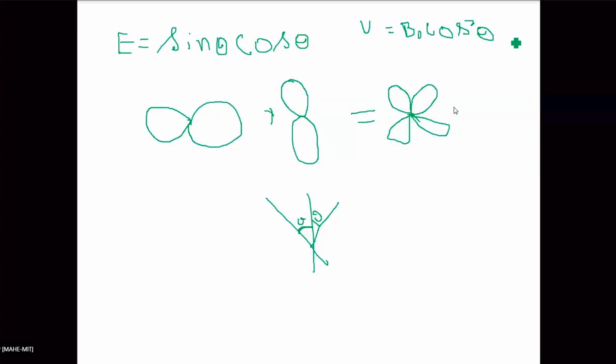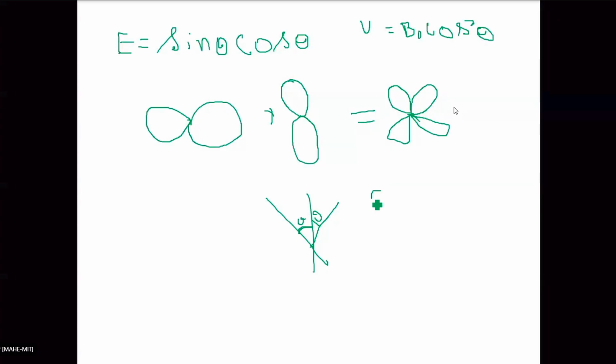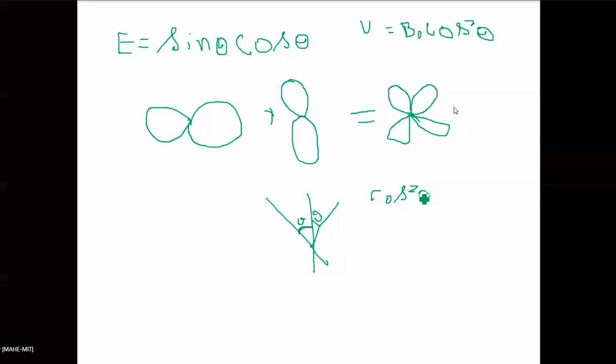Then the half power point. How do you find the half power point? How do you find cos squared theta at the half power point? Equate it to 0.707? No. Sir, cos squared theta is equal to 0.5. You have to equate it to 0.5 because it is a power pattern.